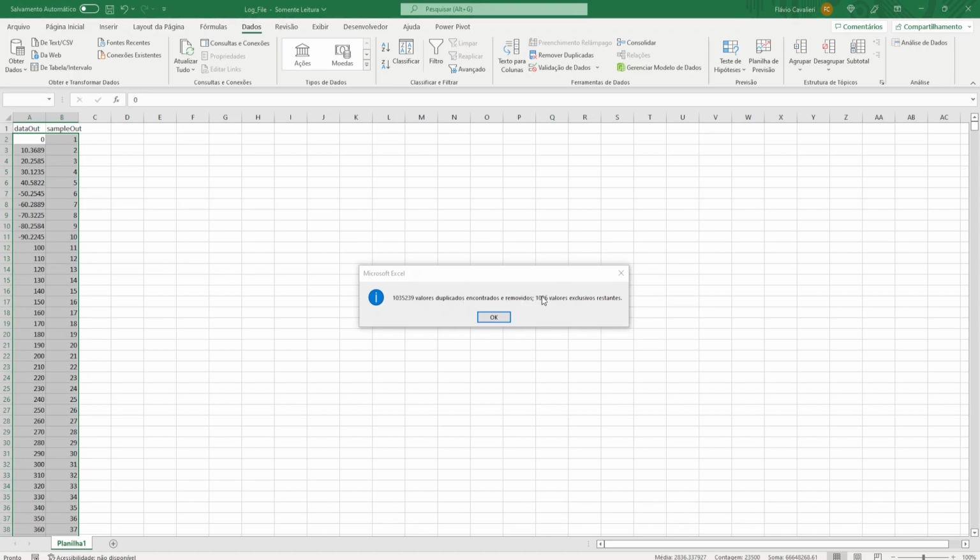Sometimes this value here can be smaller than 1026, but it depends on the recording process in the Cube Monitor feature. So in the Cube Monitor, as you could remember, we use some delay, 25 milliseconds delay to generate the toggling values, and to give some time for the Cube Monitor to save the spreadsheet values. Sometimes they can leave out some values. This can be important or not.